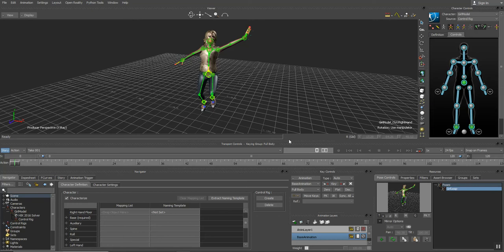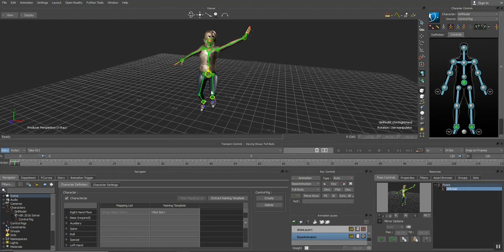And what this will do is, so now if I reset this, if I go back here to stance and set her back to her T pose, if I want to get back to that pose again, all I have to do is deselect this, say that we're back at T pose, nothing is selected. If I select all of the joints again and double click on this pose, it'll put her back into that pose that we just created.